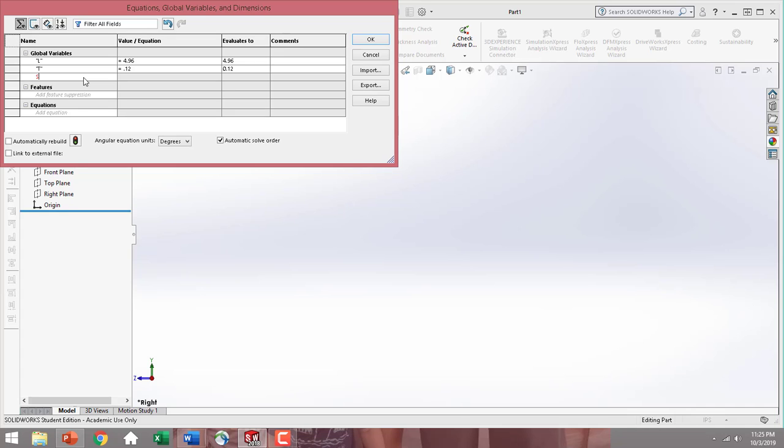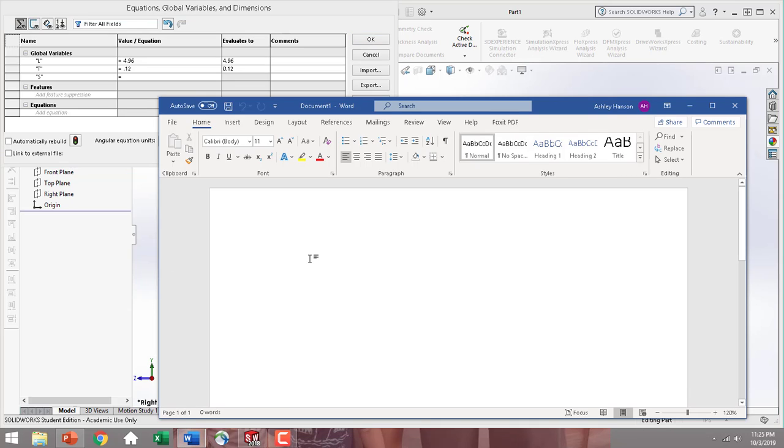Now this one is a variable space, so we need to solve for s. So if you're looking just at this quickly, it may look like it's hard to solve for s, but this really is a simple equation. So we take our overall length, we have our overall length equals, now we have 9 t slots, so 9t plus 8 s's. So now we just solve for s.